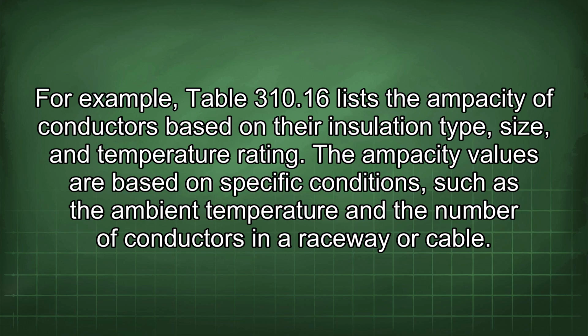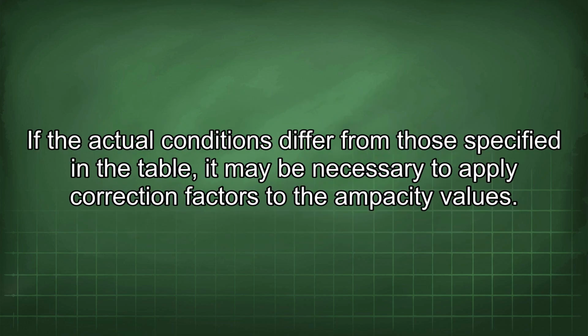The ampacity values are based on specific conditions, such as the ambient temperature and the number of conductors in a raceway or cable. If the actual conditions differ from those specified in the table, it may be necessary to apply correction factors to the ampacity values.